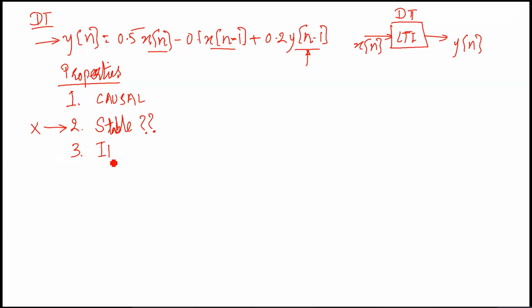The impulse response becomes infinite. If this term was not there, then this would have been an FIR system, because to compute the output we would just require present and past inputs, a scaled sum of that. But to compute the output here, you require present and past inputs and also some previous output. This is a feedback term. You have to add the previous output scaled by some factor to get your output. So this is a feedback term.